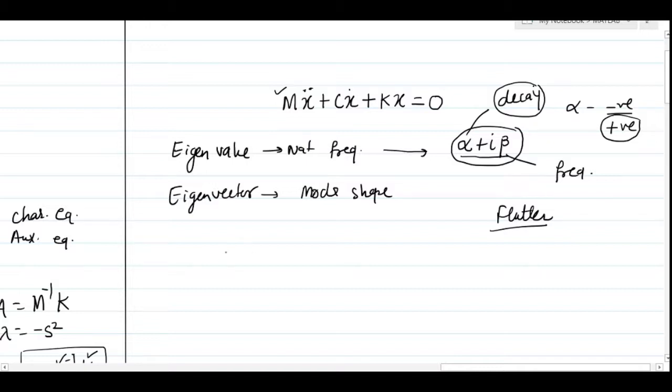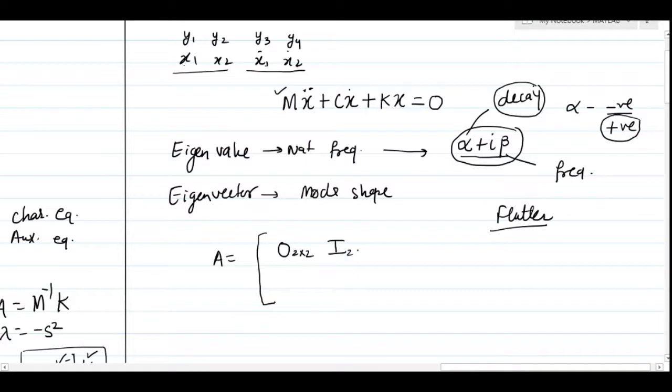So here you simply remember the coefficient matrix you derived using the state space formulation. When we solved the state space formulation, we considered four parameters: x1, x2, x1 dot and x2 dot. This part we have already covered in our previous lecture. So instead of using two displacements and two velocities, we defined four states y1, y2, y3 and y4, and we replaced the entire equation considering this, and there we derived one coefficient matrix, and I'm writing here this coefficient matrix.